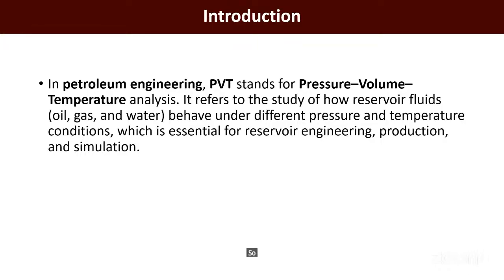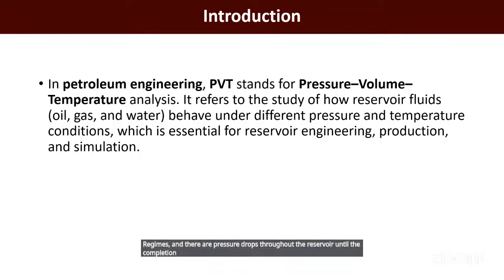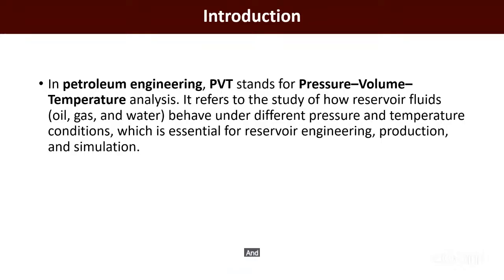So, in general, in petroleum engineering, PVT stands for pressure, volume, and temperature analysis. It refers to the study of how the reservoir fluids, oil, gas, and water, behave under different pressure and temperature conditions, which is very important for reservoir engineering, reservoir production, and simulation, because we are producing fluids from the reservoirs under different pressure regimes, and there are pressure drops throughout the reservoir, into the completion, into the wellbore, and into the surface. With this pressure and temperature